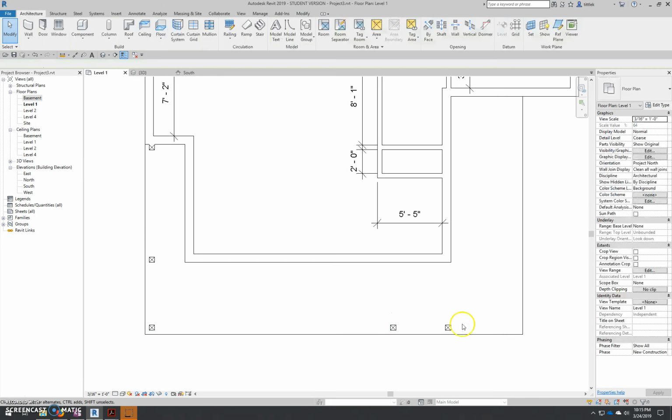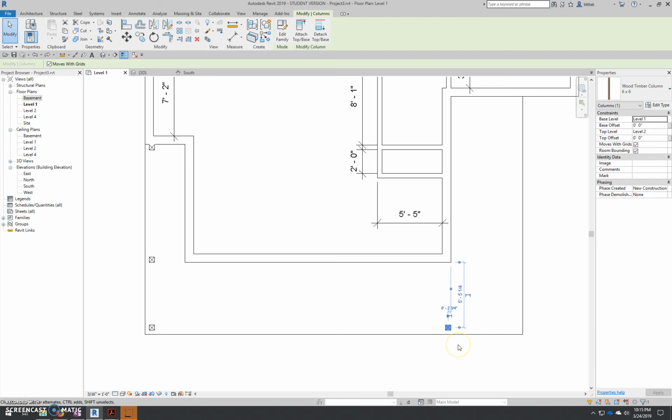Now, what I just did there, let me do that again. What I'm doing is I'm selecting this. Here's another way to create or copy something. I'm selecting it. I'm hovering over it till I get the move button. I'm clicking and I'm moving, but before I click, I'm going to hold Control and then click and drag.